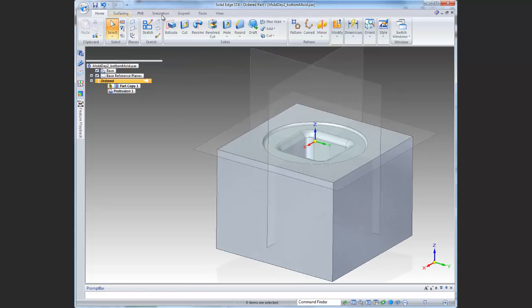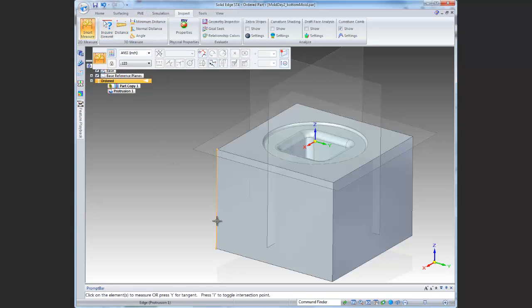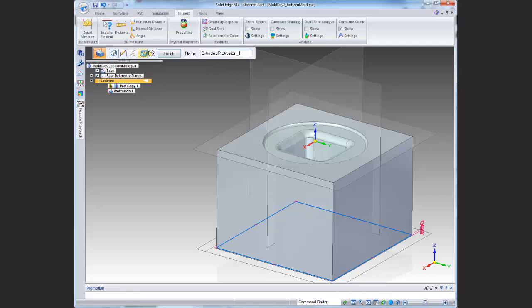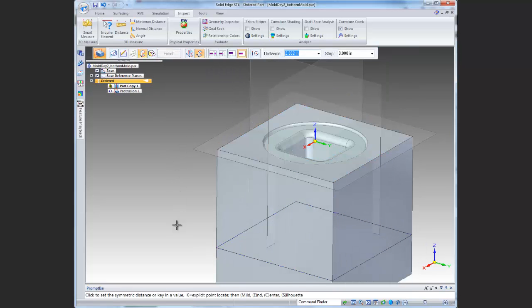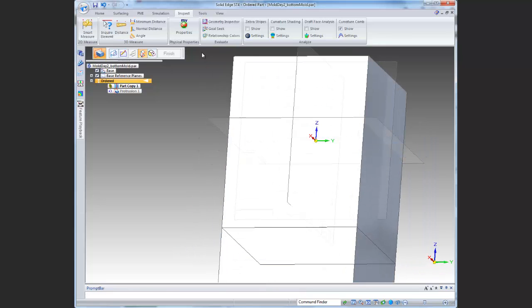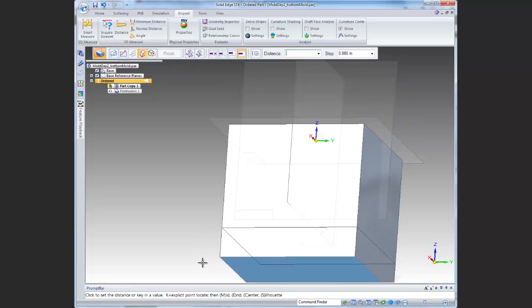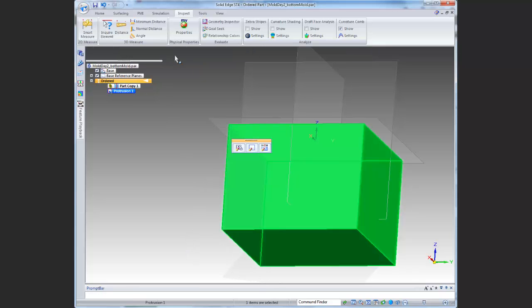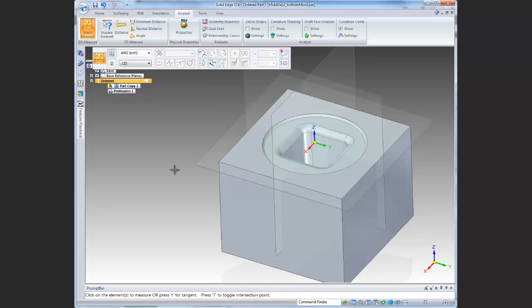Some things kind of looked weird there, so I'm going to inspect it again. And to be honest, if it worked or not, I must not be able to type. It's closer. Somehow it got a slight error. Did I not extend it the right length? Oh, you know what? It was doing a symmetric extend, wasn't it? All right, turn off symmetric extend. Now 0.05. Gotcha. So it did half of it, which I knew something looked weird. There we go. So now it's 3 inches.